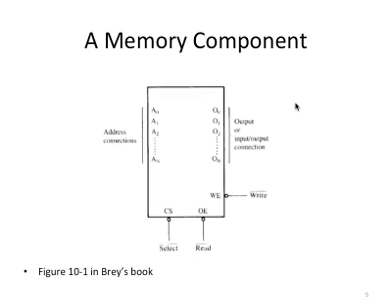Essentially, if you are reading data from this memory chip, you need to do output enable. Often this OE is also active low, so you need to put a logic 0 to make this chip output data, to perform the read operation.